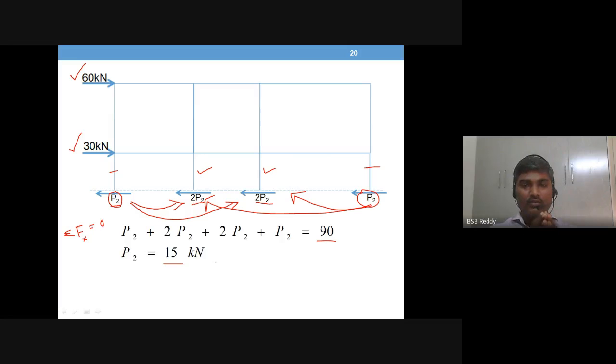Okay, so step 1 calculation we are doing now is to find shear force in all the columns. You have 12 columns here: top story 4 columns, middle story 4 columns, and bottom story 4 columns. In total you will get 12 values.